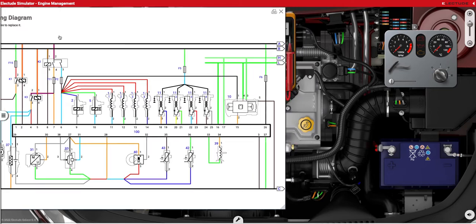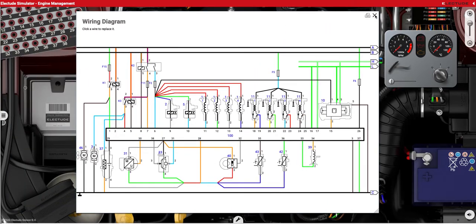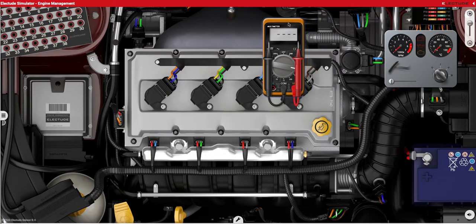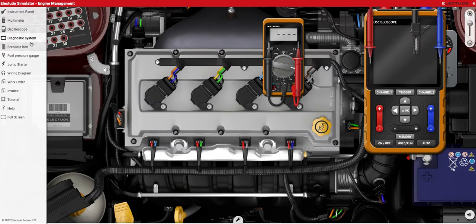Although it might be just as easy, if you have to do any testing at a component, to just zoom in on the component, and if you need to unplug it, you can do testing at the component itself, or you can back probe the pins. Either way. So that's about it as far as the tutorial. Be familiar with how to use the multimeter. For those that wish to use the oscilloscope, I will just give a brief tutorial on that.